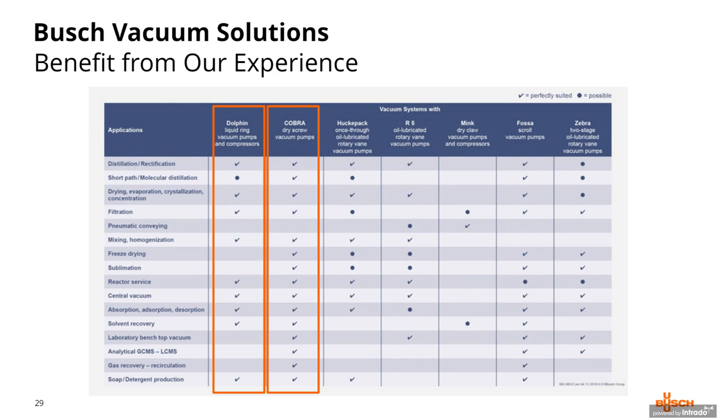Another technology that's used often in the pharmaceutical vacuum world is vacuum boosters. Now they work together with the vacuum pumps, as Theodora mentioned, and they do that to increase the capacity and ultimate pressure, up to a factor of around 10. It works similar to a supercharger that you might see in your car. It works by compressing the gas and pushing it against the discharge seal.